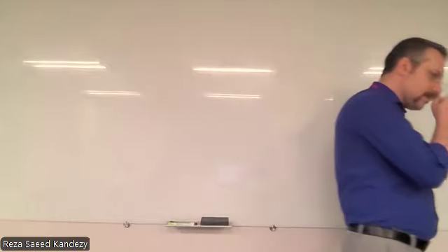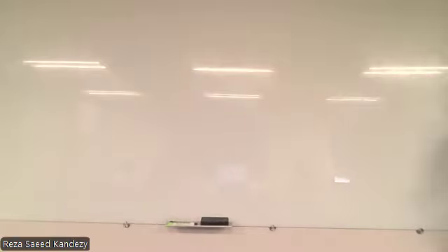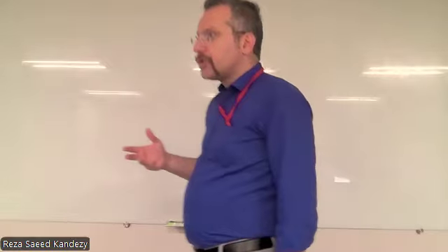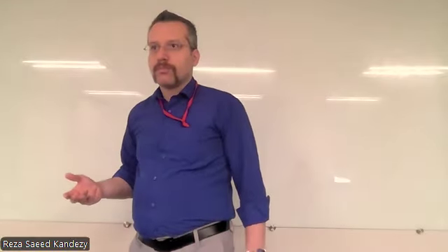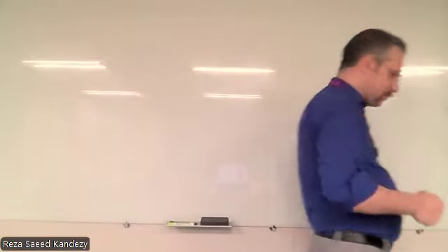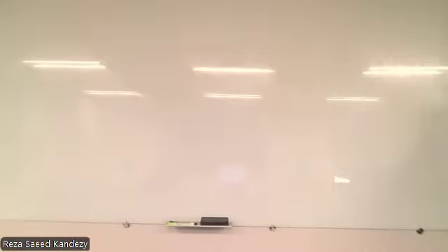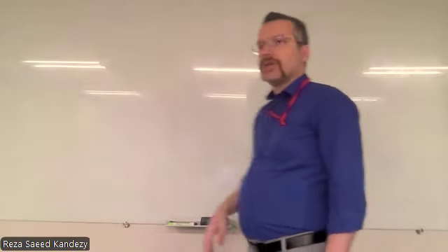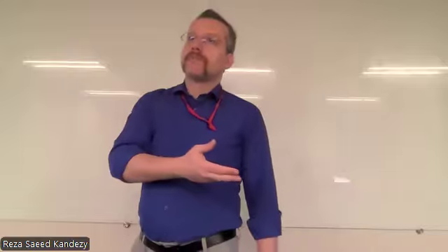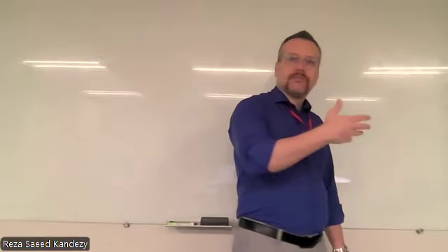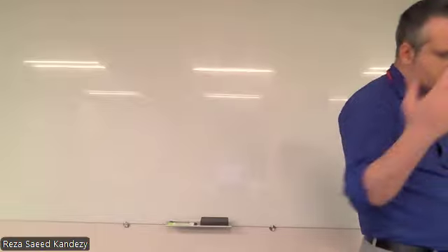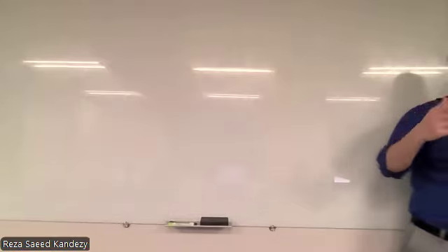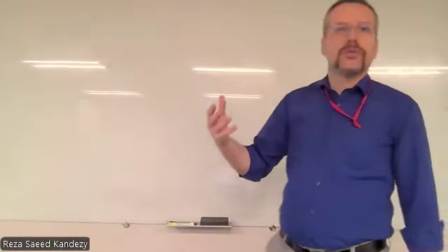So through time, they might change. One example would be the control system that helps you manage the temperature of the room. We have a measurement of the temperature. Then we have a certain electrical circuit, the control circuit, that is going to manage it. This is a specific control system that we designed, like the most famous one, a PI or PID control system.